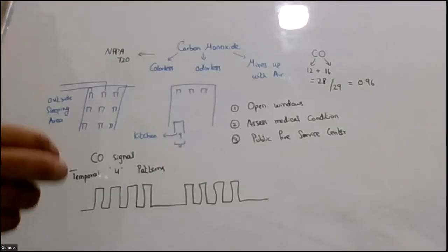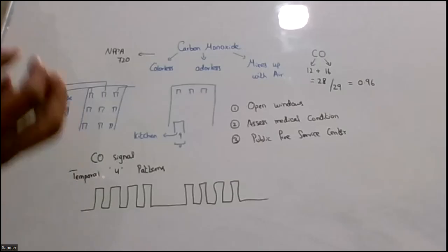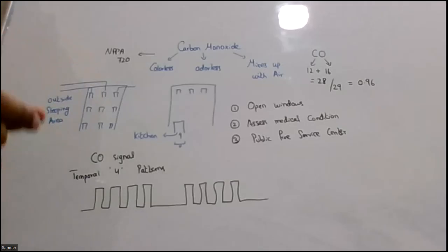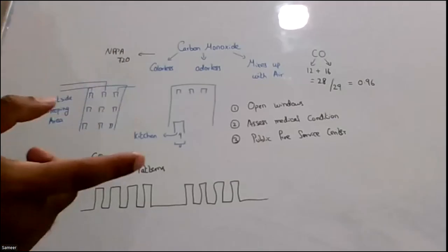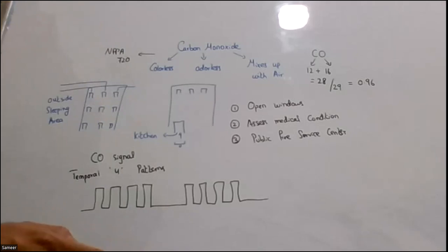Sensitivity of a smoke detector should be 2% per centimeter, meaning that in the chamber, when any type of mist or smoke accumulates inside the chamber, 2% per centimeter sensitivity should be there as a minimum for the detectors. If it's greater than 2%, it means that the sensitivity is lower. It means there's a delay in detection, and again a delay in activation of the system.